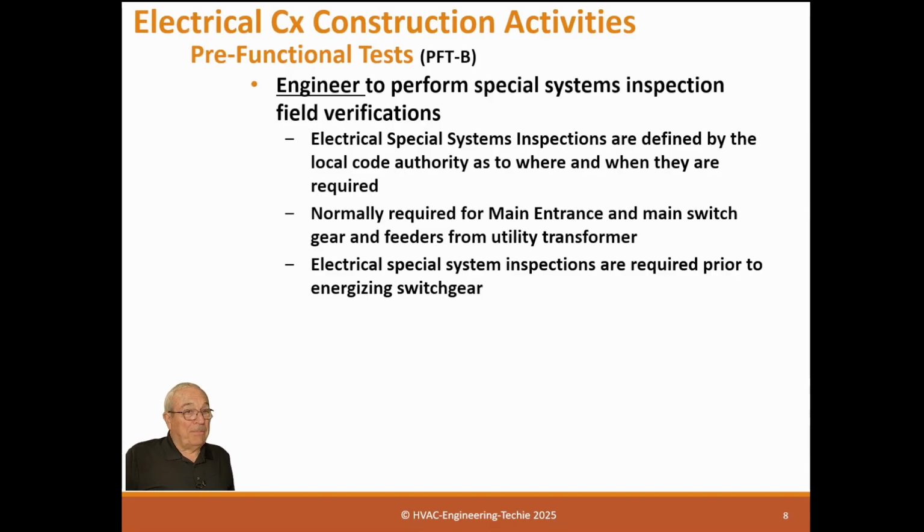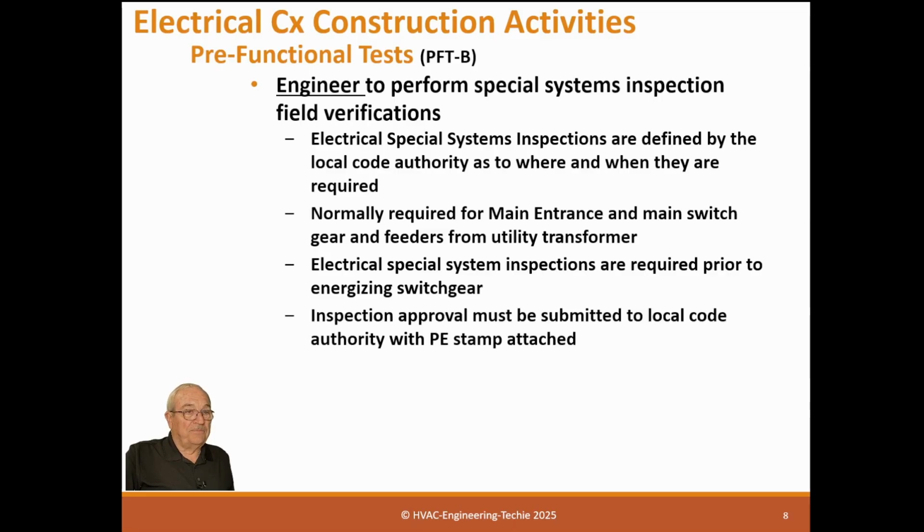So that can't happen, and you don't want it to happen. The electrical contractor was taking the lifting eyes off the switchgear, and the guy took one off and laid his wrench down across the bus bars and never retrieved it. And no one ever measured the bus bars after that to notice that they had a direct short. And not only did they have a direct short between two phases, it was a big wrench, and it had all three phases shorted, so it was a problem.